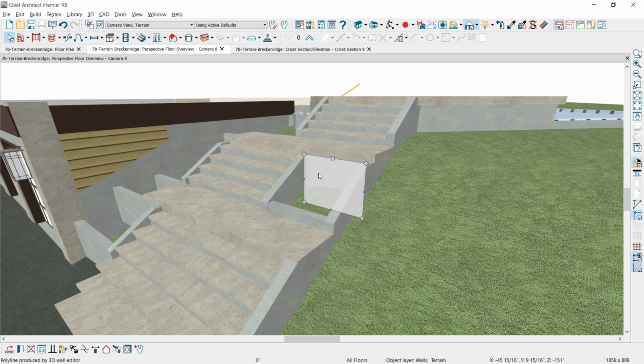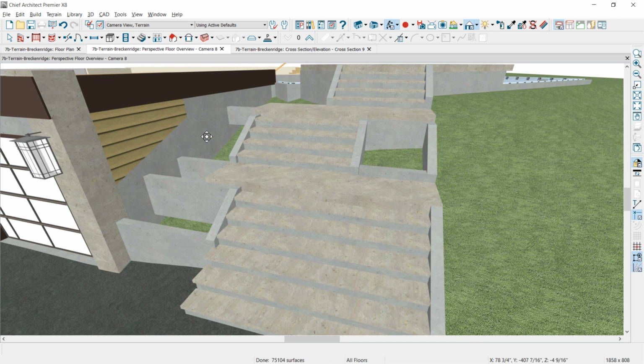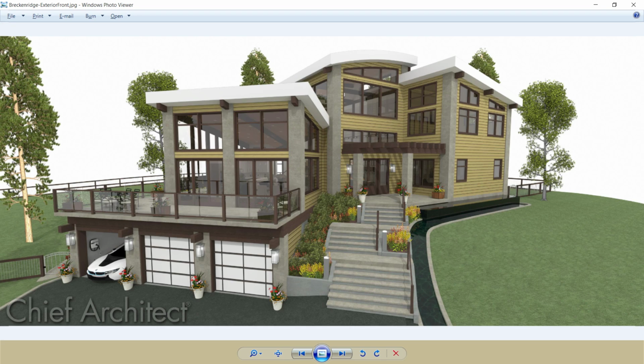Alright, so I kind of skipped ahead and finished editing the walls the best that I could, and you can see the relatively well-formed walls that are going to support the stairs. Now I need to go in, and in the 3D view here, add the terrain fillers for the plant beds. To fill these planters, I'm going to use a terrain feature, and I'm going to create the fill for the planters on the right side of the stairs and then on the left-hand side of the stairs.